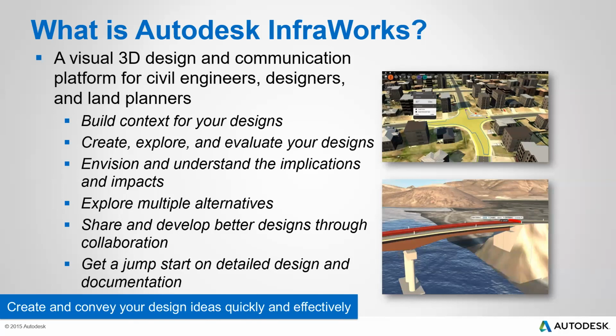And once you are able to start up your project, Infraworks comes in with the detailed design and documentation tools, which means that you can apply various design criteria when designing a road, apart from just conceiving and visualizing how that particular road will look like once completed. You can exactly see if maybe you want to apply a design speed of, let's say, 50 if it's an arterial road, or let's say 80 if it's, for example, a superhighway. So it means that you can at least know before you move into your detailed design stage.